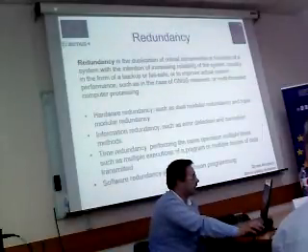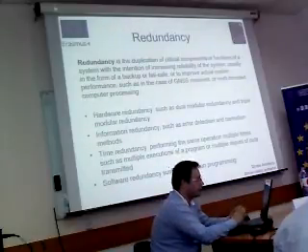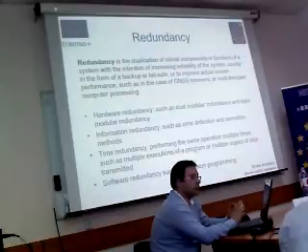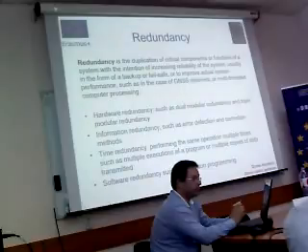The next important thing in safety is redundancy. So in many safety critical systems, such as, for example, fly-by-wire or ground systems in aircraft, some parts of the control system may be, for example, triplicated, which is formally termed triple modular redundancy.